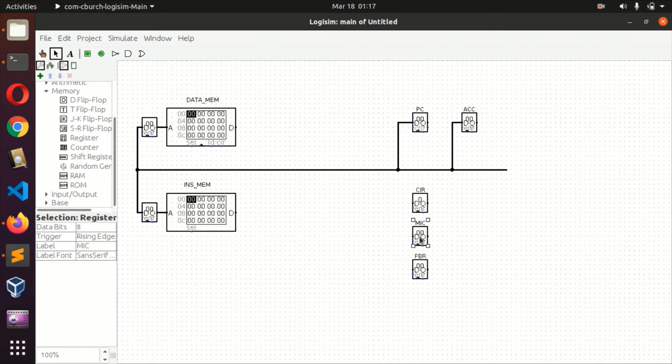And then for the micro instruction counter, we are going to use 3 bits. The choice of 3 bits is because overall, our instructions will not require more than 8 steps to execute. That's just an assumption for now, we just assume that's how it's going to be. Now for this feedback bit, I will also make it 3-bit, and the reason for that you will see later.